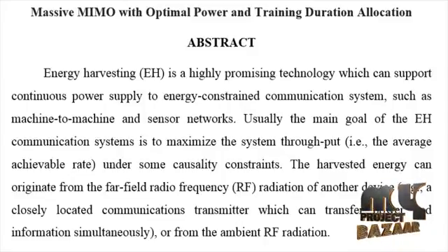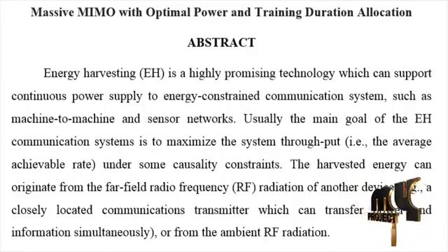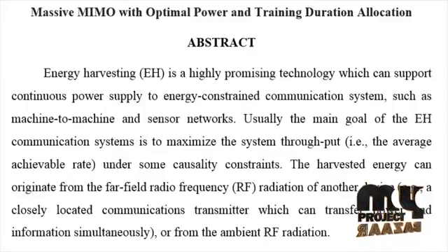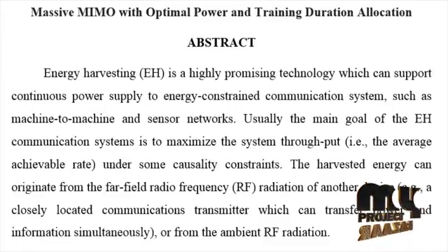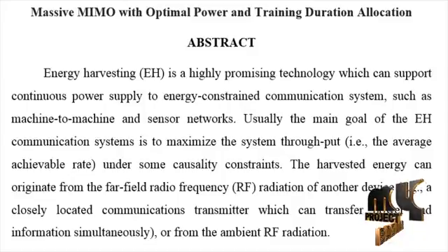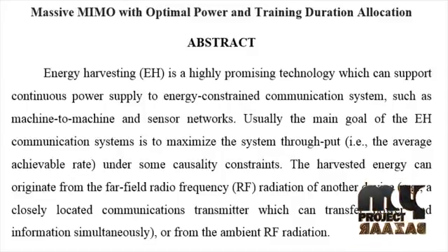Finally, for an interference channel with more than 2 transmitters, it is also possible to specifically design transmit signals so that the interferences are always constrained at confined subspaces at each receiver. This allows the receiver to efficiently reject the interference. This idea, known as interference alignment, has been shown to achieve significantly improved multiplexing gain for the MIMO interference network, where both the transmitters and the receivers are equipped with multiple antennas.